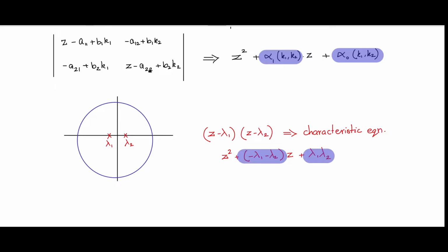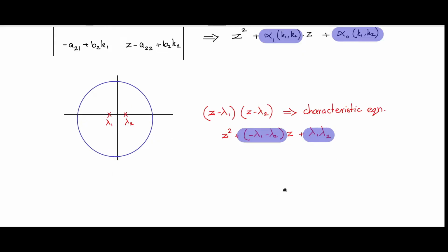It is cumbersome even for a 2 by 2 matrix. So if there are a very large number of states, it can become difficult to do by hand. So there are algorithms. There are two algorithms. One is Acker. Both in MATLAB and Octave, you will see this Acker, and even in Python, Acker, coming from Ackermann's algorithm or Ackermann's formula. The second one is Place. Place is also another roots finding algorithm, where you give the desired pole location, you will obtain the values of k1 and k2. So both Acker and Place are pole assignment tools, and you can use that.